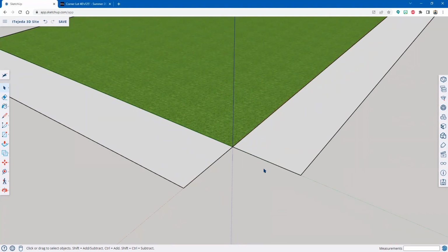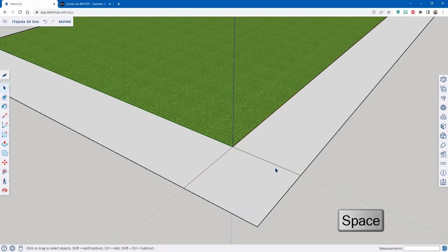I'm manipulating it. So what I'd like to do now is draw a rectangle, but it's actually a square. But I'll still use my keyboard shortcut and I'll type R. And I'll start my rectangle from this endpoint, one click, and do not click and drag, just simply click. And then I click over here. And now I have a couple of extra lines in here that I don't need to see. First of all, let me tap my space bar. I have a line here, which I don't need anymore. And I have a line right there, which I don't need.